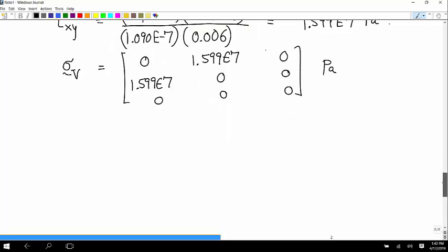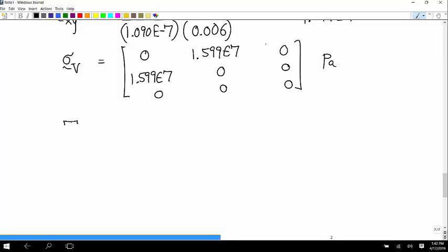And then the last one is the torque. This is a thin-walled cross-section. So we're using the formula that says the capital XY shear stress is equal to negative torque divided by 2 times the thickness of the wall times the area at the median of the wall.